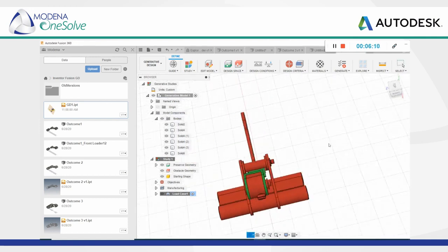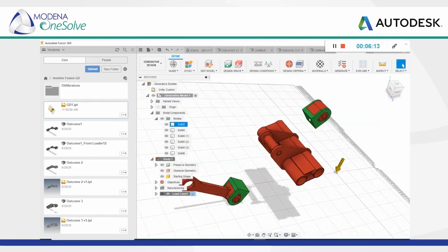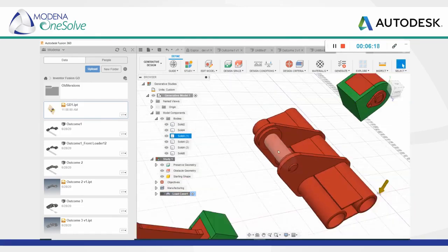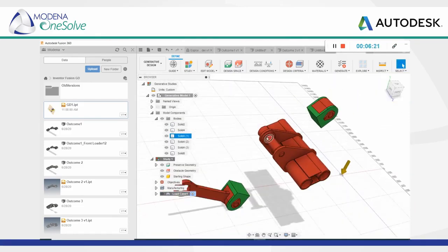Now, what's key over here is you can actually see there is a piece of preserved geometry missing. Okay, so what's going to fit around this pivot axis over here? That hasn't been designed. So like I said previously, we can transfer data from Inventor to Fusion via the Fusion desktop connector, and it bridges a live link. So what happens in Inventor will then populate through to Fusion 360. So remember, this is a bi-directional workflow. It's not one way. Changes made in any of the applications will reflect in the file. So it doesn't just work from Inventor to Fusion or Fusion to Inventor.